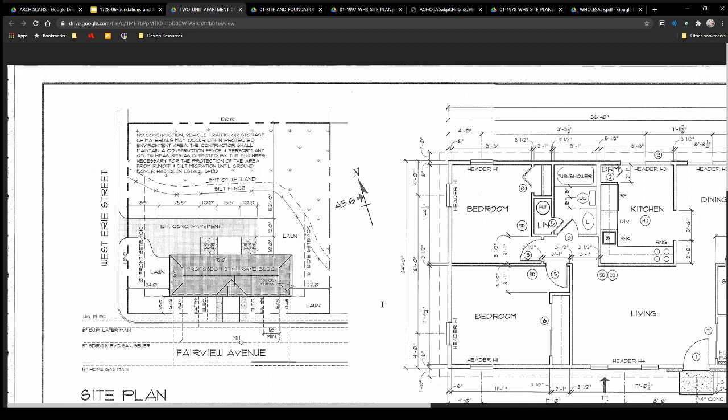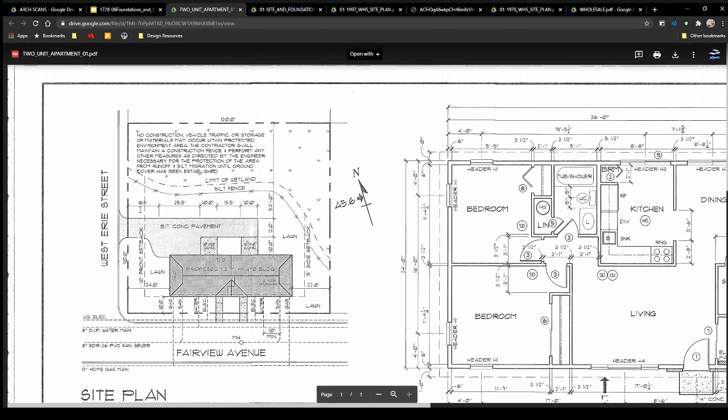And the other thing that you'll see in your drawings for your site plans are what we call setbacks. So the setback then is the area of the property you are allowed to build on. So just because this property has this heavy phantom line going all the way around, those are our property boundaries. However, we're only allowed to build within this setback area.